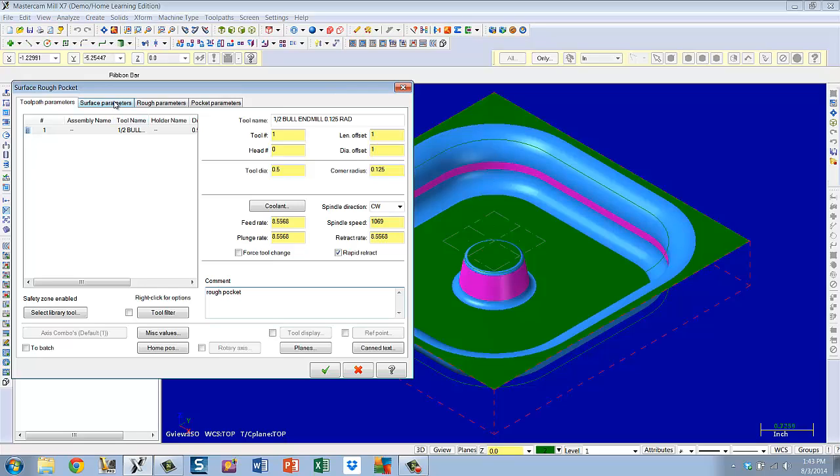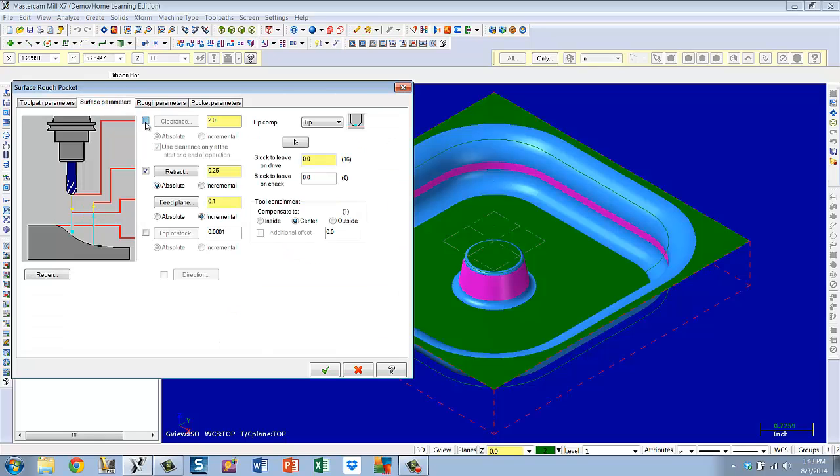So that looks good. We go to the next page in this form to fill out. Mill Level 1, we use these same parameters here in our linking toolpaths. We're instructed to leave 30 thousandths on this part. Everything else looks good.